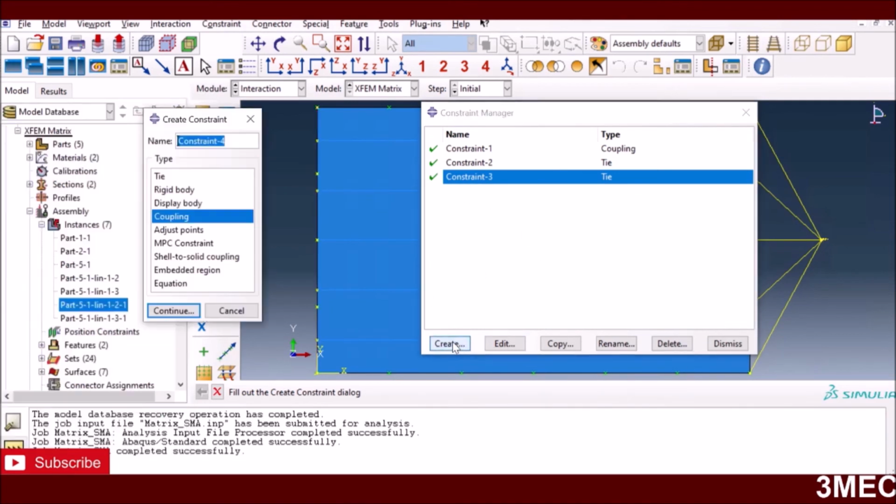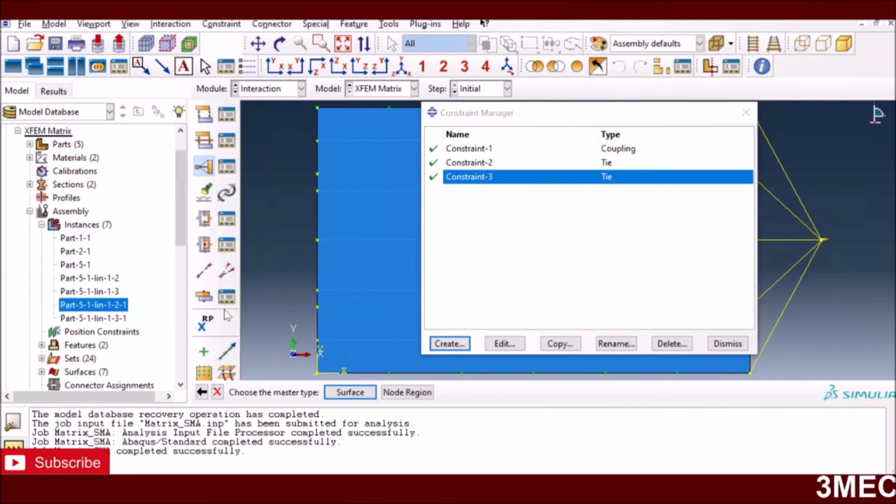So again, to create it, you just go to create constraint and select tie. When you select continue, it will ask you to select the surface or node region, and then master or slave. So again, as I told you, the stiffer surface is generally recommended to be used as the master surface, so I have done it this way. I'm going to cancel it because I already have these interactions here.